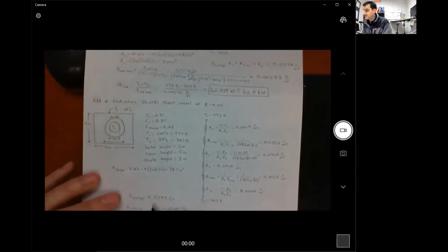I always think it's interesting to take that number and just look at where it's coming from. So where's most of that resistance coming from? Well, if you look at these terms, the vast majority of that number is coming from these two right here. So the two surface resistances of the shield are providing the vast majority of that number. You add these two alone together and you'd get like 0.484 1/meter squared. So anyway, I always think that's kind of interesting. It's kind of a qualitative description of what's going on. So there's our surface and space resistance.